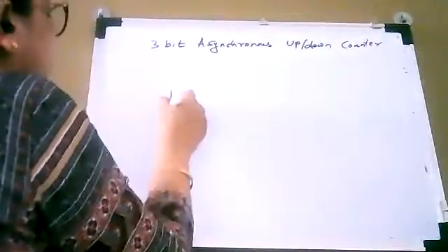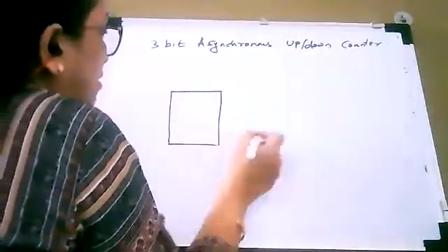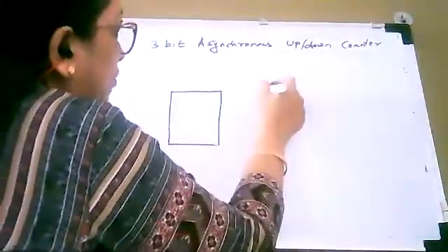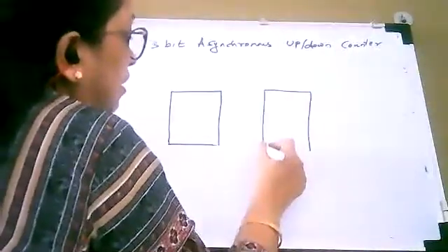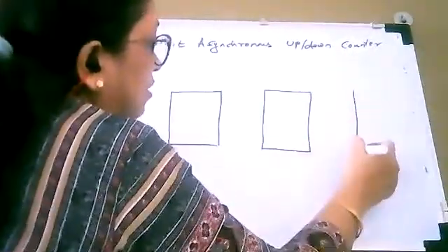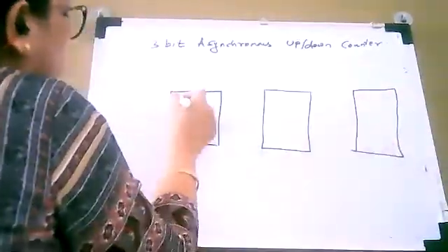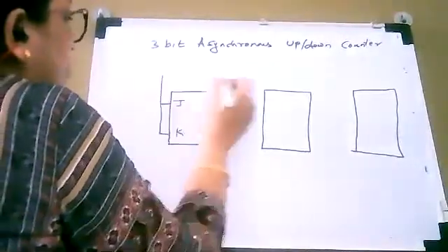Okay, so this is also using 3 flip-flops. It is able to count 8 states, but in both directions. So we have to use additional logic for that. First let us draw the flip-flops. We are going to use JK flip-flops in toggle mode.